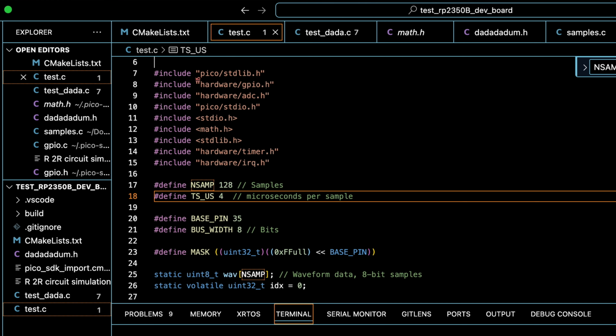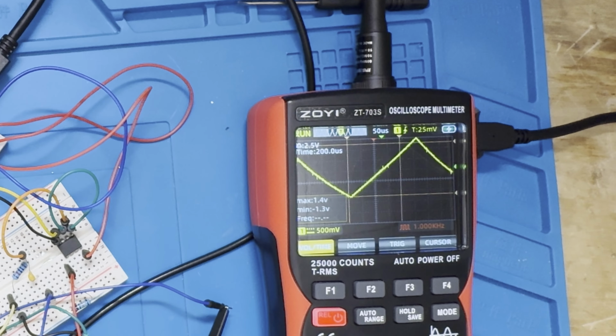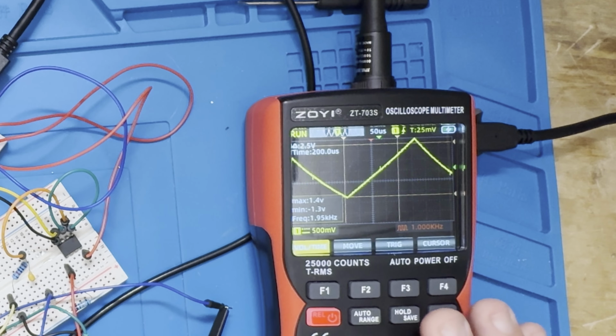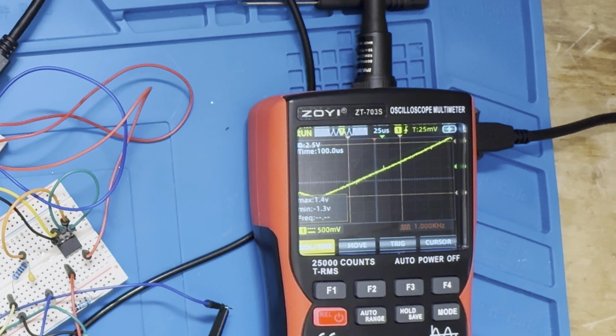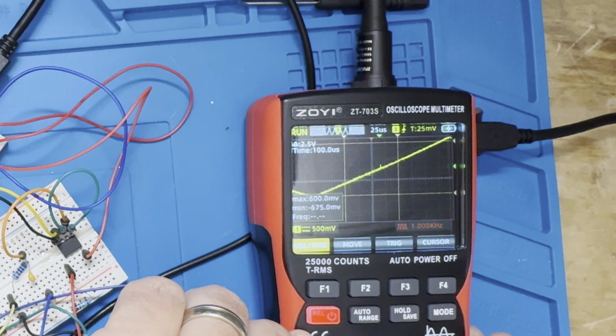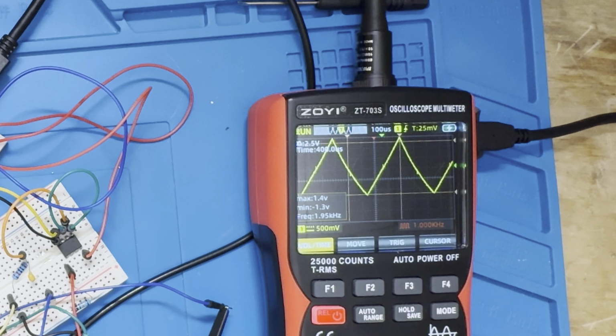4. So this should change the frequency, make it go down a little bit. So that's a nice one. This is actually a pretty smoothly varying function, so those 256 digital levels give us a good amount of granularity, and the fact that we have 128 samples per waveform means that we don't really have any kind of jaggedy steps here. But what happens to the sound and what happens to this waveform as we change the number